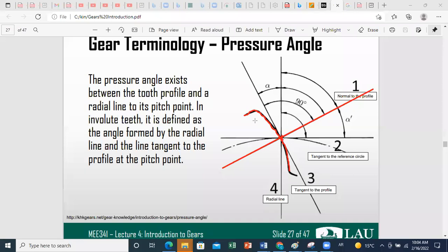and this force transmitted will be perpendicular to the tangent line to the involute. We'll see together in the next slide a clearer figure where it's shown how the two teeth are in contact, and then we can define the tangent line to contact and the normal line to contact. We can say that the pressure angle will represent the angle between the line of force transmission.